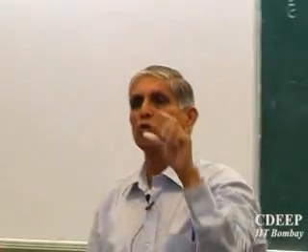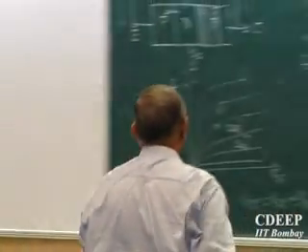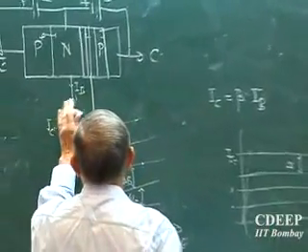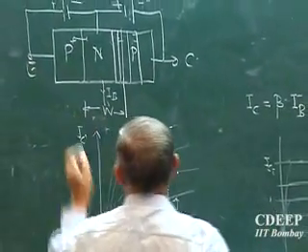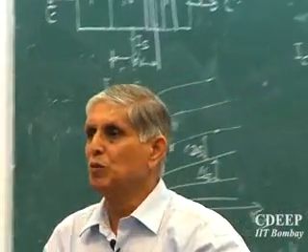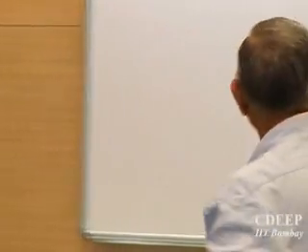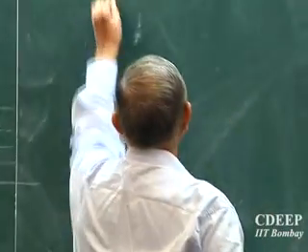Though base doping is larger than collector doping, it's not very large, not as much as the emitter. So it is still lighter doped compared to the emitter. As I said, 10 to the power 16 or 5 times 10 to the power 16 is the base doping. Which means some depletion will always come on the base side. This is your initial W, the base width. But as I increase VBC, the reverse bias, what is the actual base width now?